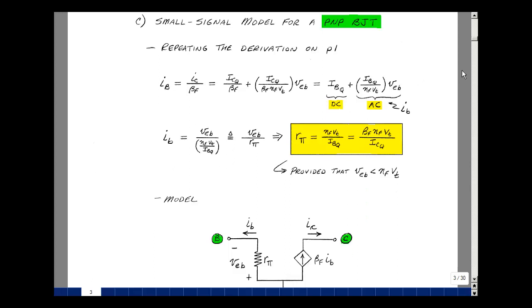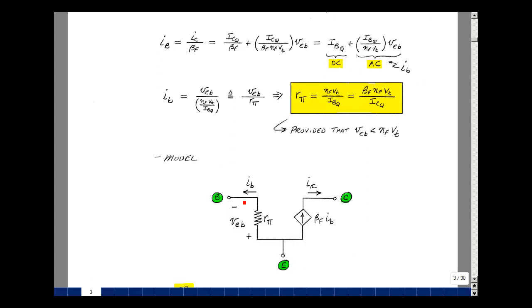Well, everything is reversed. We're going to reverse the currents for AC, and we're going to reverse the voltages for AC. The same model with our base, collector, and emitter, but when we draw a PNP transistor in the schematic we saw in Chapter 3, we generally drew the emitter on the top. The reason that they do this in magazine articles and application notes is that they usually show current flowing from the top of a drawing to the bottom, that current coming into the emitter and out of the collector. So let's flip the model over.